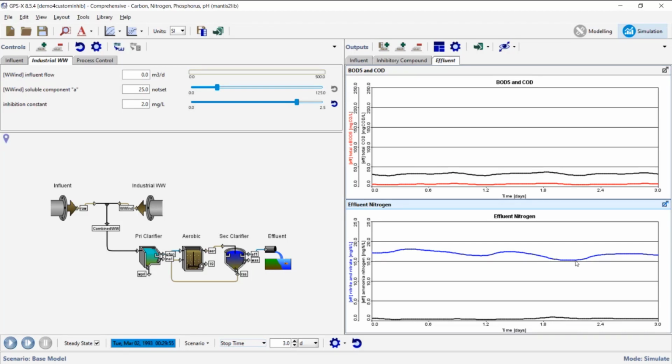There's a little bit of a dip. You can see the dip in the nitrate here, at the same time as the lack of full nitrification was happening. Right? Okay, so that's a way, if you had any particular data, you could actually use that to calibrate what this number should be, right? So if you knew that the ammonia got up to 10 or something, that would be something you could calibrate.